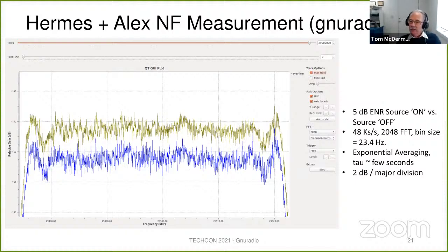We've done all of this with just an SDR receiver, a simple noise source, which only costs a couple dollars to make, and we just wired it all up in GNU Radio. So there's all kinds of things you can do with the virtual blocks and the radios. It kind of is up to your imagination, but you have a pretty powerful piece of test equipment without really spending much money.